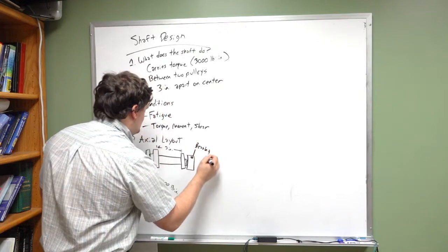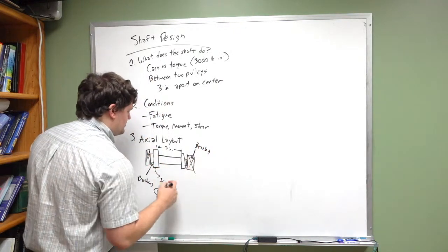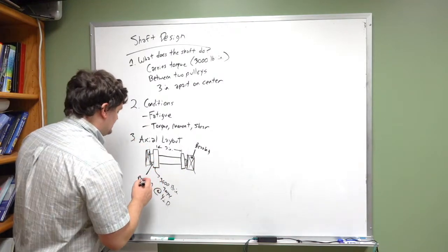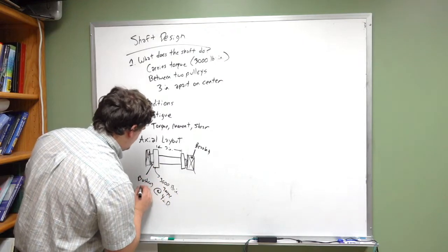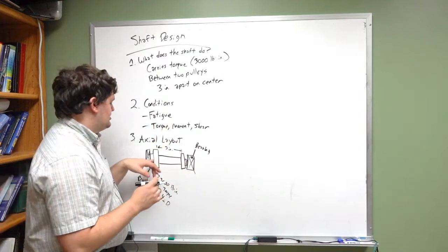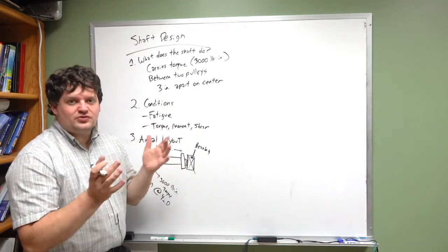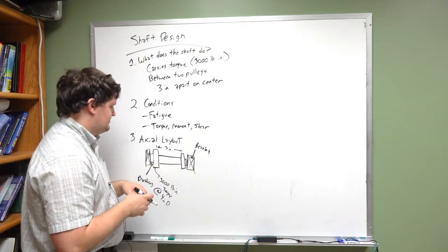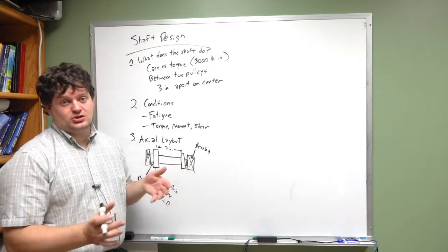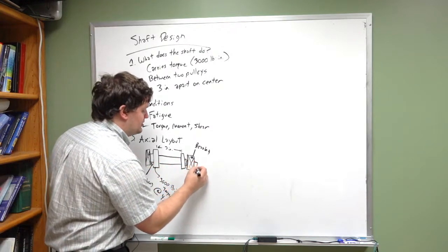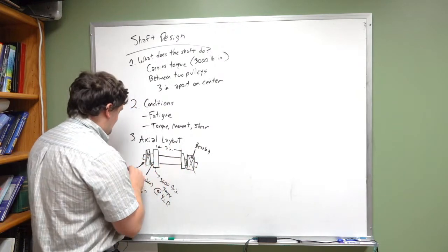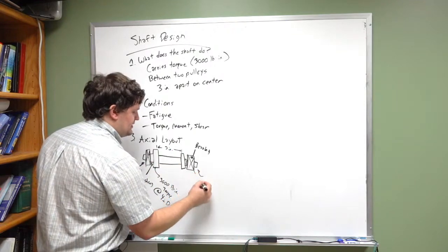Okay, so at this point we have pulley, bushing, bearing. This bushing is going to be 1/2 inch, just because it'll give a little bit of play between the pulley and the bearing, and it'll prevent them from running into each other, causing problems that way. Okay. What happens to the shaft outside of these, we don't really care about. You can make it longer if need be. You probably want to make it a little bit longer than the bearing on both sides. So maybe we'll add 1/2 inch of shaft on both sides.